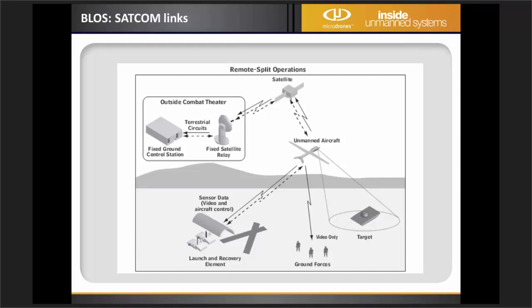So we'll launch a drone from Afghanistan using conventional line of sight data links. It gets up to a certain altitude. We flip a switch, turn it over to a Ku-band satellite in geosynchronous orbit that hits somewhere in the hemisphere, and then we essentially fiber it out to anywhere on Earth. So that way you can control the drone from Las Vegas, Nevada, 6,000 miles away with relatively low latency. But that's very expensive, and it's not a realistic solution for most of our commercial providers.